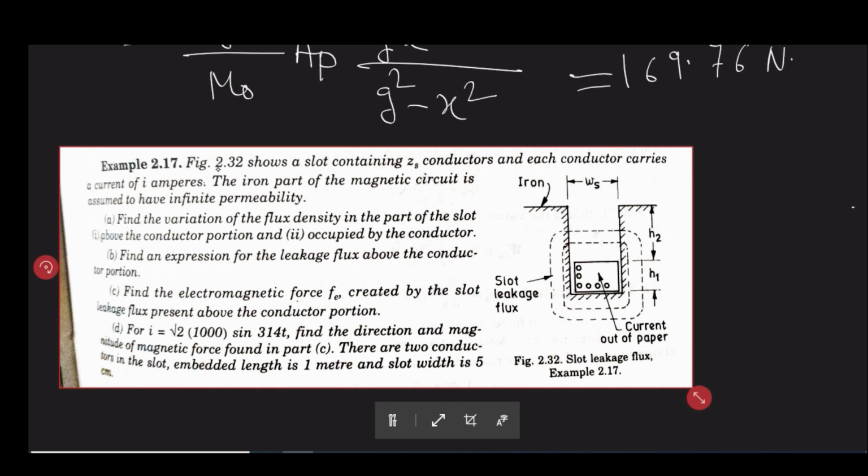We have to understand that leakage is not only detrimental in terms of loss or other things what we have already studied in our transformer, but in case of a rotating machine, or a system that is having any movable structure, leakage can also produce some torque, and whatever undesirable phenomena it will produce, all those consequences are also undesirable.